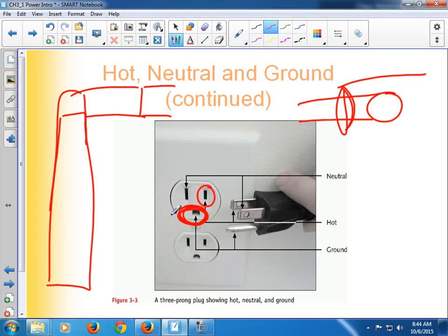Okay? There are sections of my house that are still knob and tube with no ground at all, and no electrical stuff gets plugged into those outlets. That's important. My light bulb, the floor lamp, doesn't matter. Okay? But if it comes to my stereo and I plug into that, I am hoping that my stereo lasts for a while. Okay? So I've got hot, neutral, and ground.